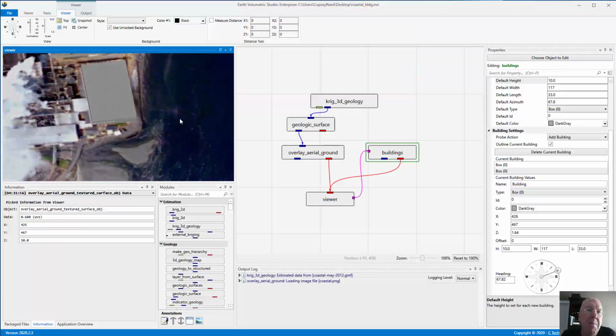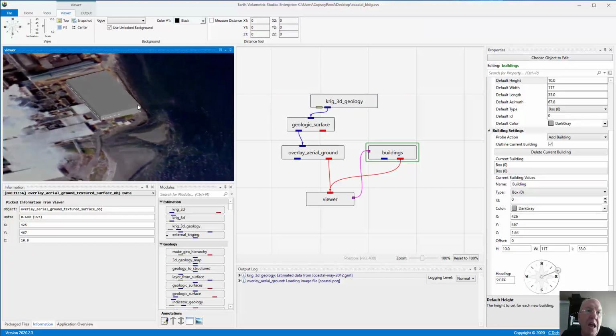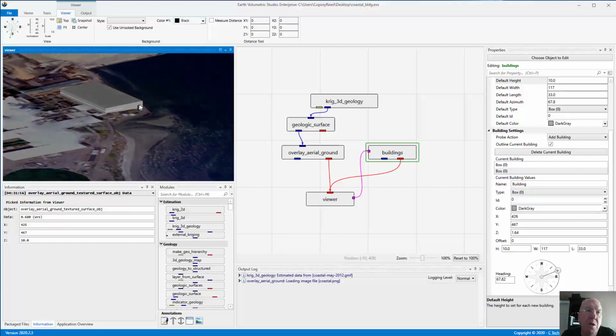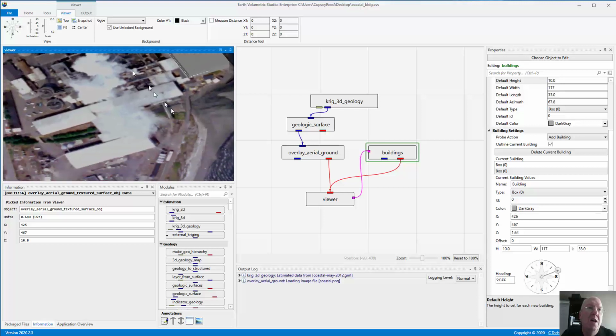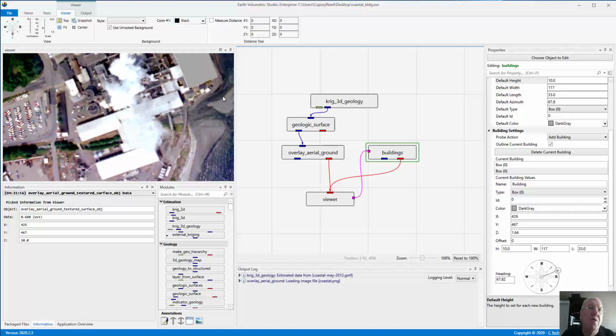So we've got a small gap between them, and we probe those two buildings. Now I'm going to do 2 more buildings before I go on to do gables, so we're just going to do the boxes first, and you'll understand why in a minute. So let's go back to a top view, and let's look over here. You can see the gabled roof here. You can see the difference in slope in the ridge line.